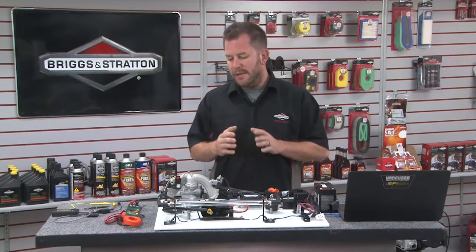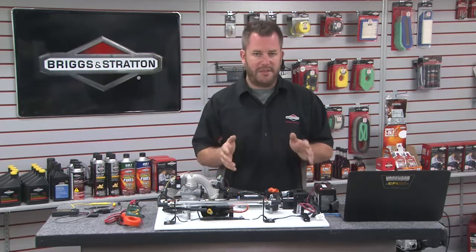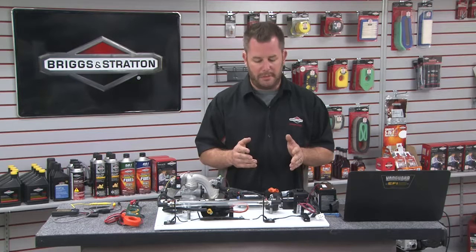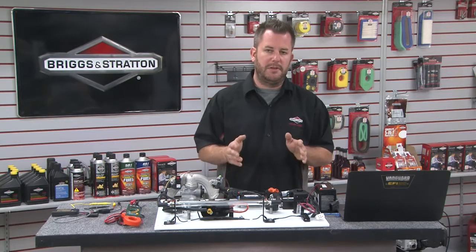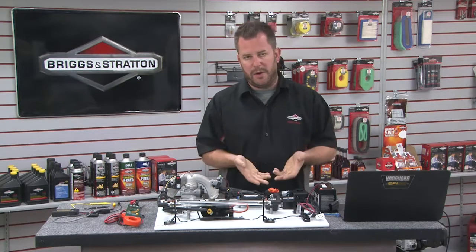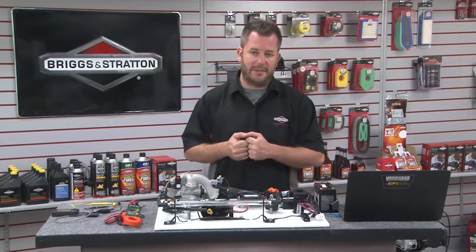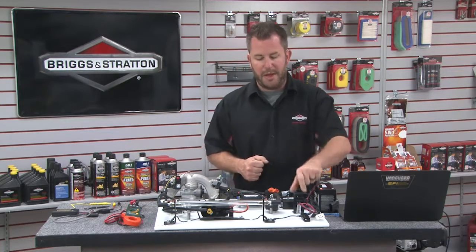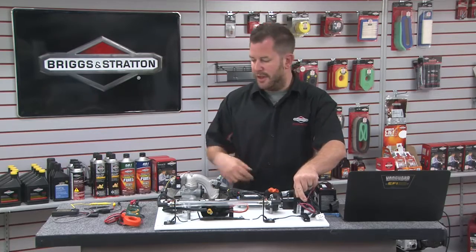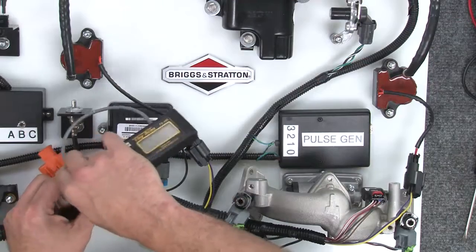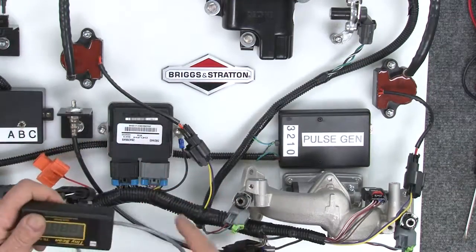So, how we begin to troubleshoot this is just like anything else. We have to read and verify whether we have a code present. Okay, so the first step here is we're going to do it the longhand way here, and we're going to read it with a Tiny Scan, measure out some of the circuits at the sensor itself, and then of course look at the laptop. So what I'm going to do first here is I'm going to turn the ignition on, take my Tiny Scan, and I'm going to read the codes here with our diagnostic data link connector here.